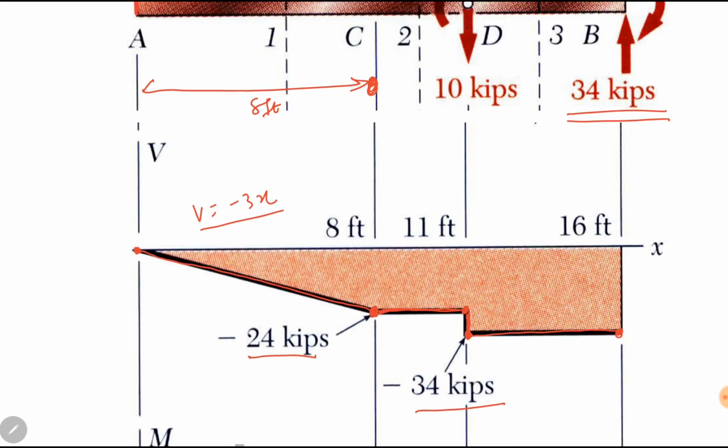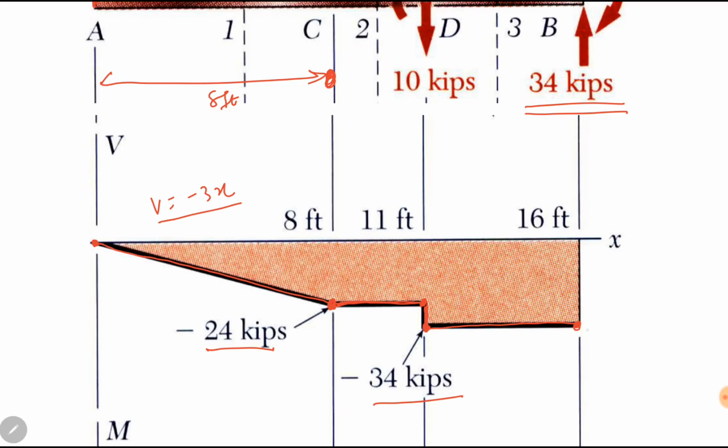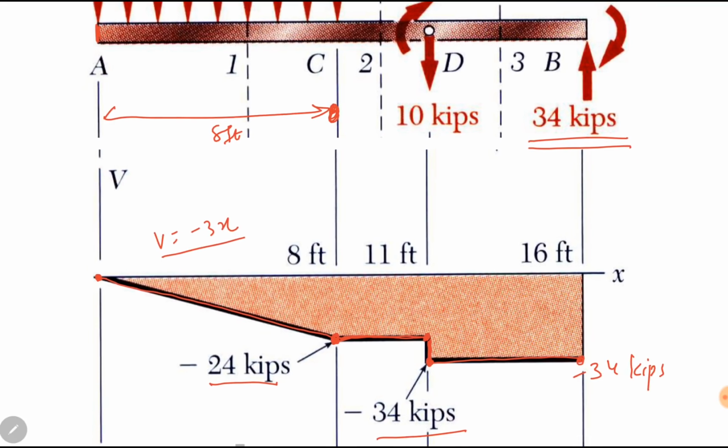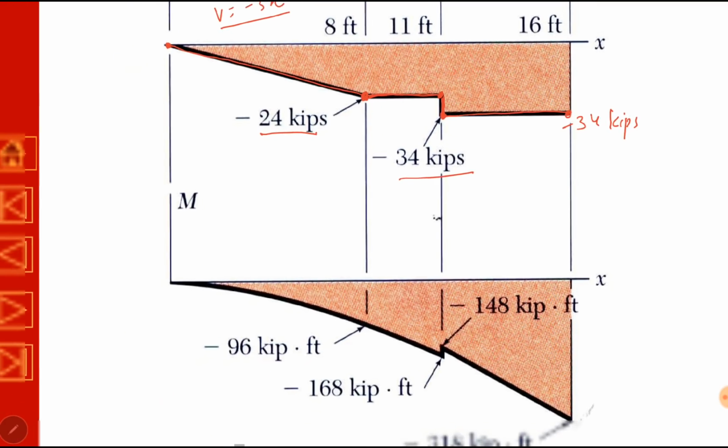It is 0, and it should be 0 because in the free body diagram there is no concentrated force at the starting point. At the end, when you reach the end and your value of shear force is the same as the value of the concentrated force at point B, it means you have drawn the diagram correctly. Okay, if we move forward, we have bending moment expressions.